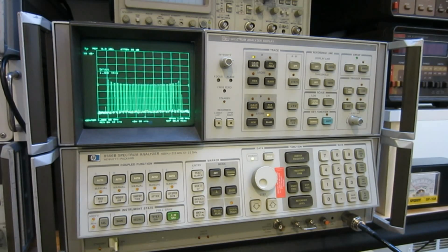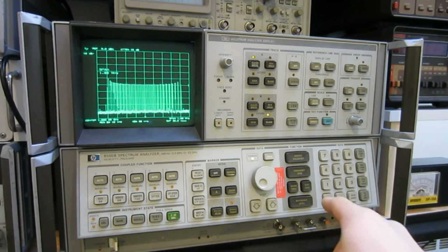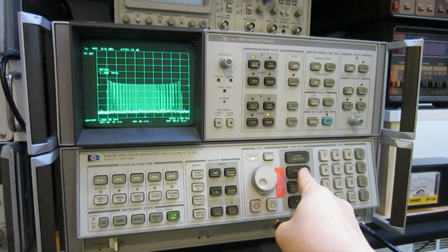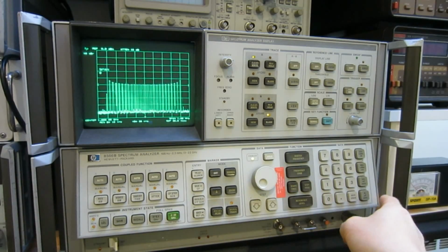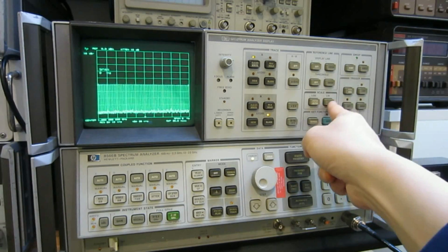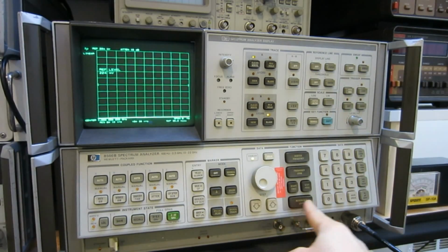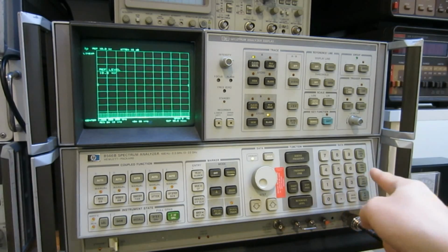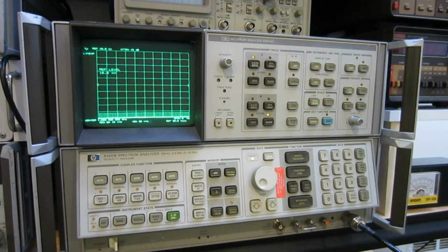And we're going to do the same thing as what we did with the AM signal. First, we set the frequency span to 0. And then we are going to set it to linear mode. We then set the reference level to 10 millivolts. So now we can see some signal at the bottom. But remember, we are right now looking at the signal that is towards the center of the filter.